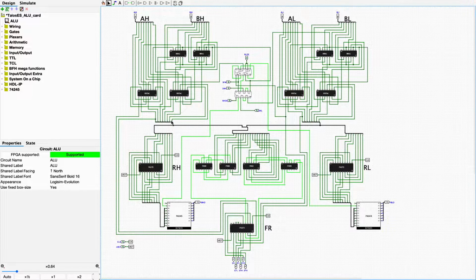Because if you do that, you have to address the registers, but then you will change the value of the registers within the same cycle in which you are supposed to be computing the previous value of those registers. So that doesn't work, you see. You have only one cycle.